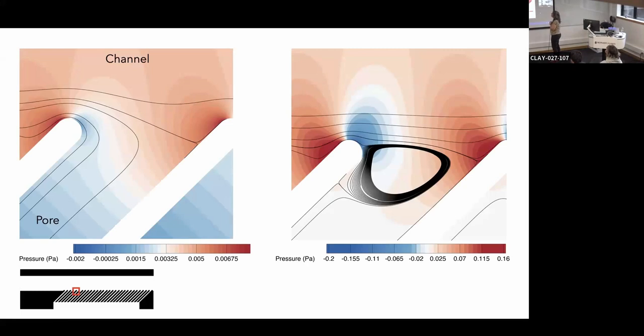Oh, that's a really interesting suggestion. So you're saying that my particle, let's say I have a bigger particle, and for some reason it gets caught in here. If it's big enough, it's actually not going to get into this part of the flow. It's going to get caught in the vortex, which means it's going to come around and then pop back out of the vortex. So we have not looked at what happens when particles cross streamlines, which would certainly be true because there is some diffusion in these problems, and this is a high enough Reynolds number that there's probably some inertial effect that will allow them to cross the streamlines. I had not actually thought about this trajectory, so that's a good one. Well, we'll have to take a look at the experiments and see if we see it.